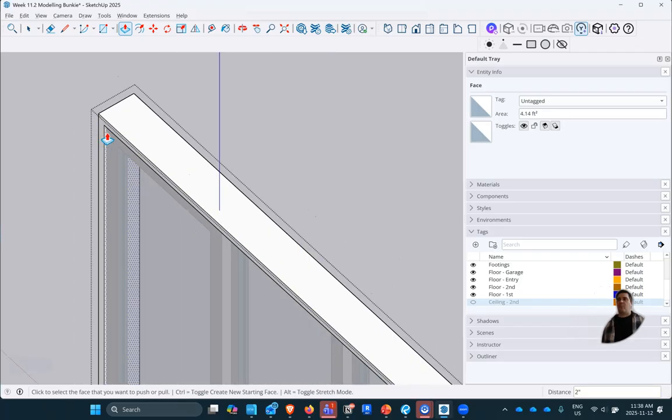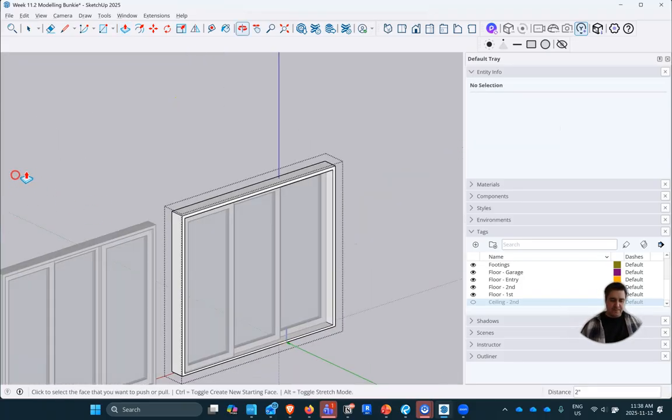And so that's one thing that we've kind of learned over the last few years, especially with doing a lot of multi-slides, is when we end up having a multi-slide, we actually go to like a 2x8 wall often, because it's just easier for the contractor to frame a deeper wall than to fur it out, or we might do a double wall. So we'll do a 2x6 wall on the exterior, and then we may do another 2x4 wall in there somewhere to get that thickness that we need for a multi-slide. Obviously, it's pretty simple with 3 panels. It's not that thick. But if we have like 4 or 5 panels, it could be like 12 inches wide and becomes really thick. So anyways, that's kind of how to do the multi-slide.